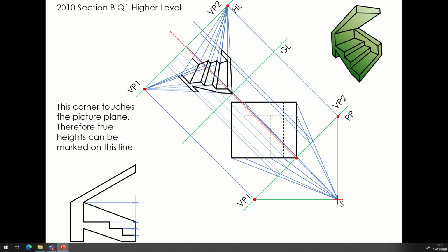We can then take our back corner here, so that would be this point here, down and up, and that gives us enough information to give us the plinth portion of it here like that. So, all we've been using there is just going to our correct vanishing point and using our previous point to build on that. I mean, getting our location by joining down to our spectator and bringing it up, and getting our heights using our vanishing points to move us across in that direction.